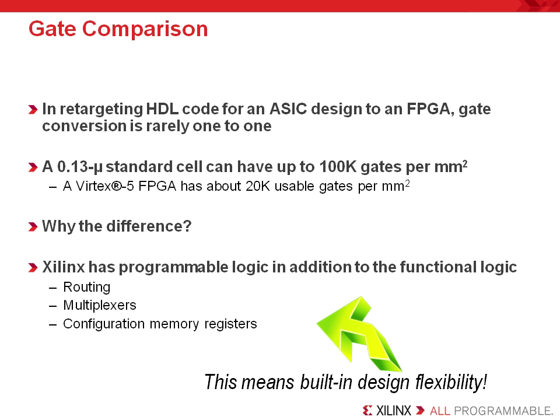As I mentioned earlier, FPGA makers don't give users access to all of the gates. In fact, customers don't use all of the functionality and gates built into the FPGA. Built into the device are various programmable resources that are used for routing signals and configuring the FPGA. Likewise, some of the dedicated resources, like the dedicated muxes, carry logic, etc., go unused. This takes some of the room that is available on the die and simply wastes the gates.